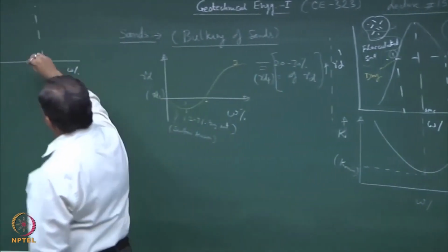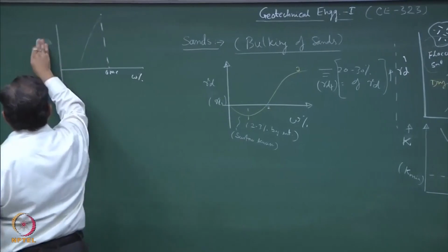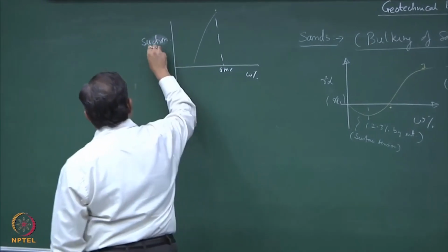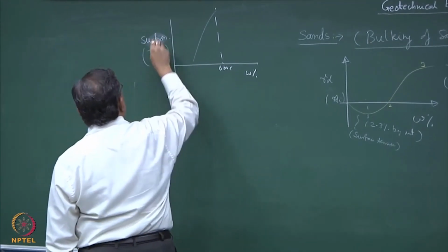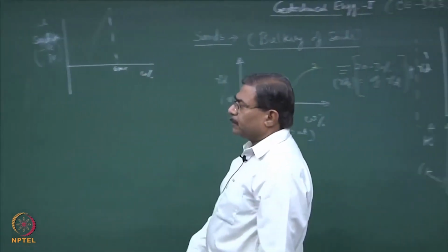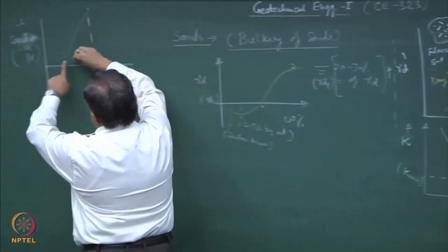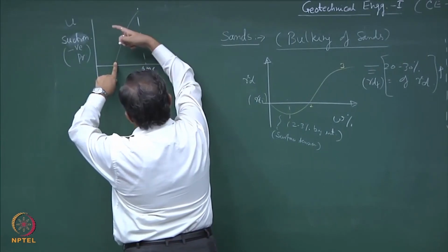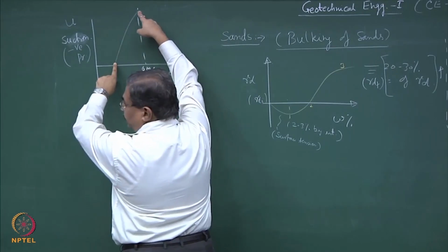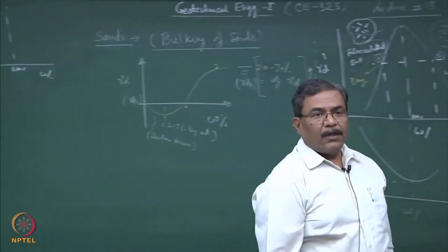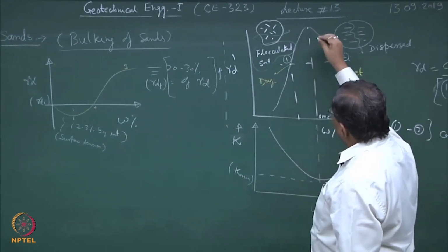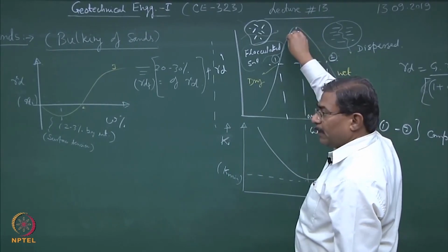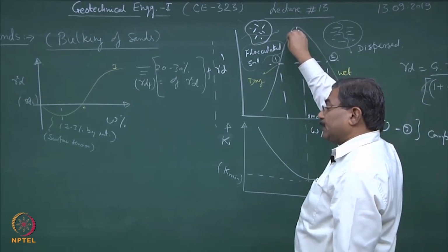So, the pore water pressures are going to be, not pore water pressure, let us use the word suction, negative pore pressures. What's happening is the more and more you compact, the more and more air gets expelled out, the suction increases. At OMC, this is the maximum possible moisture which the system is having, but just to left hand side of this, the system has maximum possible suction in it.